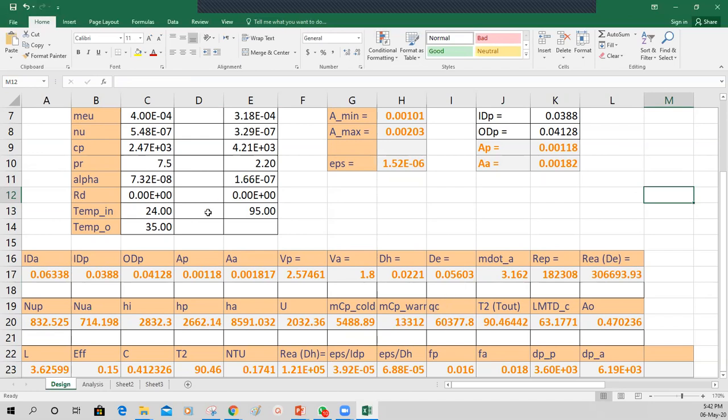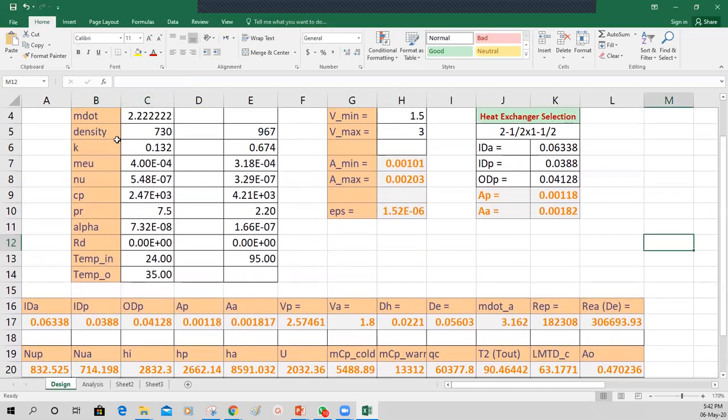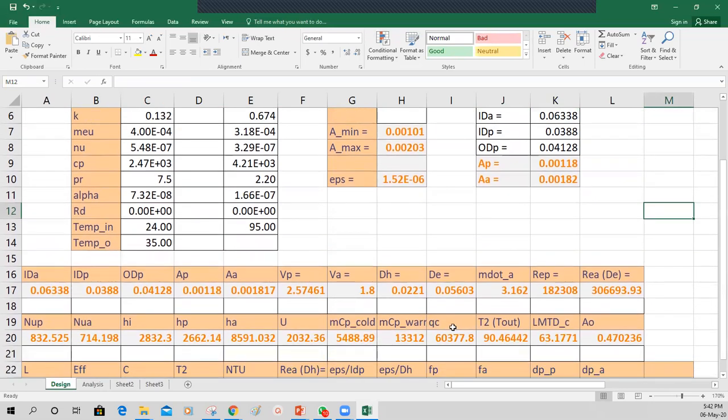So our kerosene is the warm fluid. For the kerosene, we have the mass flow rate, we have the Cp, and we have the delta T. So we can calculate the Q here. So we calculated the Q here. And the same Qc, we equated it with Qw. Qc equals Qw. And what is Qw? The mass flow rate of the warm fluid, which is the mass flow rate of water, times the Cp of the warm fluid, which is the Cp of water.